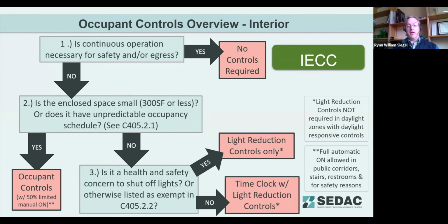So that could either be an auto on to 50% or manual on to 100%. So health and safety is not an issue in this particular area. And so since we have occupant sensing controls, we don't need our time clocks.